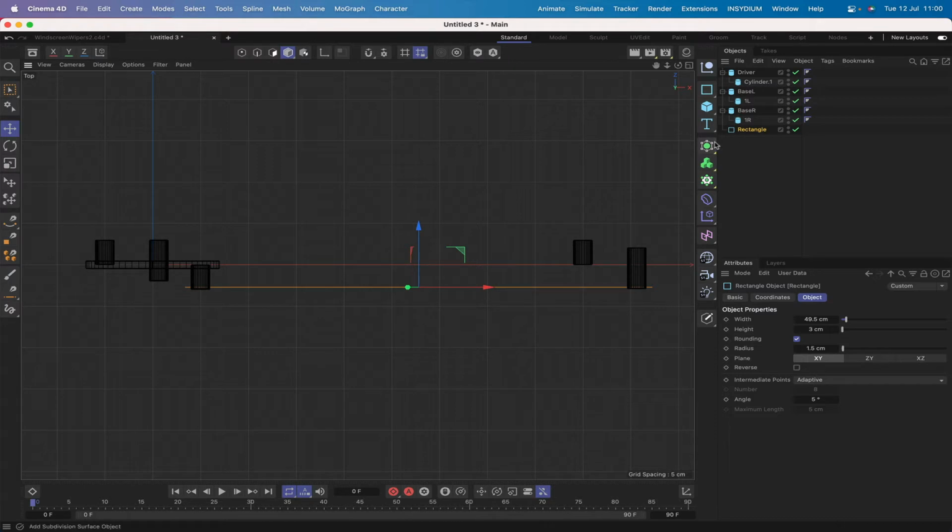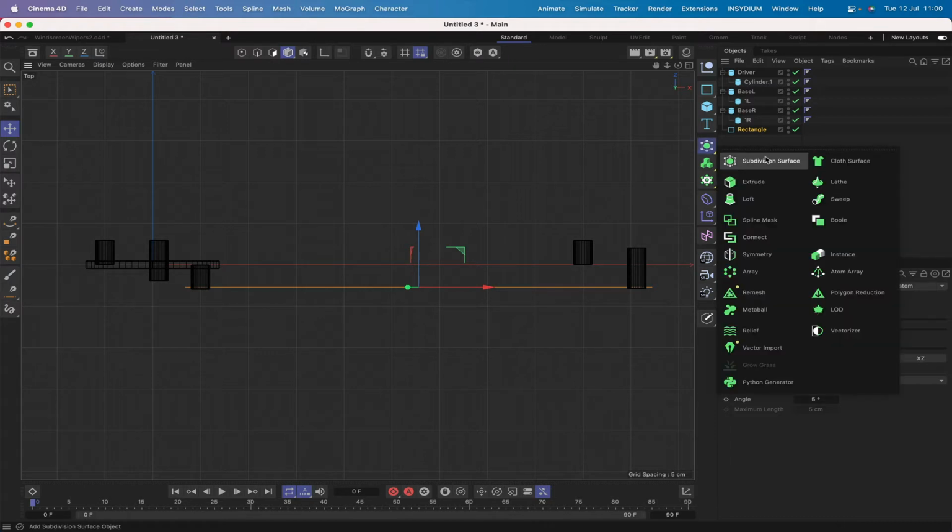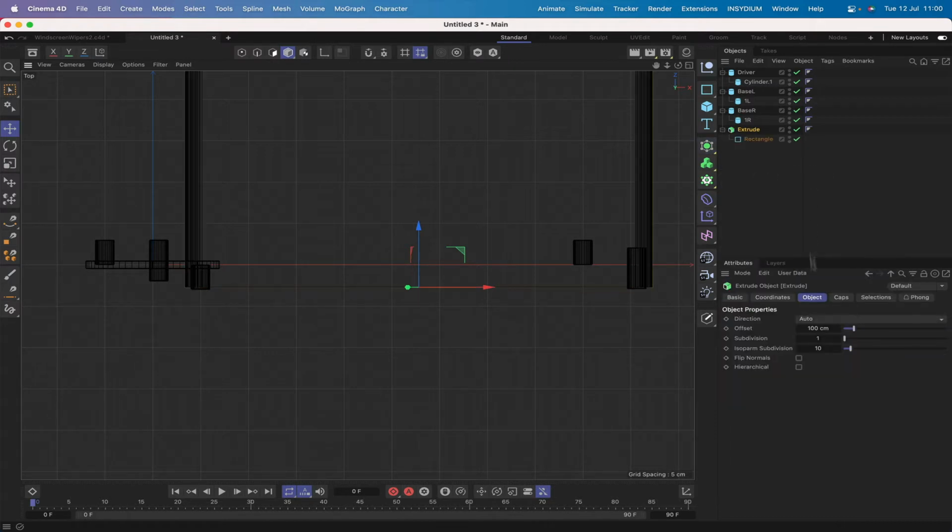And then we can think about dropping this into an extrude. It's going to be way too long. We want it something like 1 or even 0.5, I think will be fine. That's 5 millimeters, which is quite a sturdy bar. So yeah, 5 millimeters is absolutely fine, and we'll leave that as it is. I think that's okay.